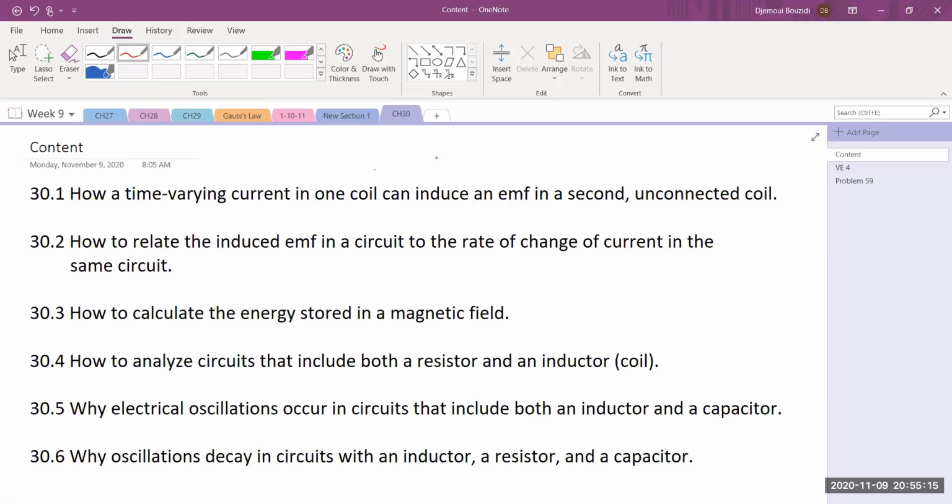So in other words, since that magnetic field is changing with time, its flux is going to change with time, because the flux is basically the product of the magnetic field with the area. So if the magnetic field is changing with time, its flux will change with time, which means that it's going to generate an EMF. So this could be something that is negative in a circuit. When you're doing your wiring, you have to be very careful. Sometimes that may be a problem, and sometimes you take advantage of it. That's exactly the purpose of this whole chapter. So what we mean by inductance in this case is how a circuit will induce effects in a second circuit. That's exactly what inductance is.